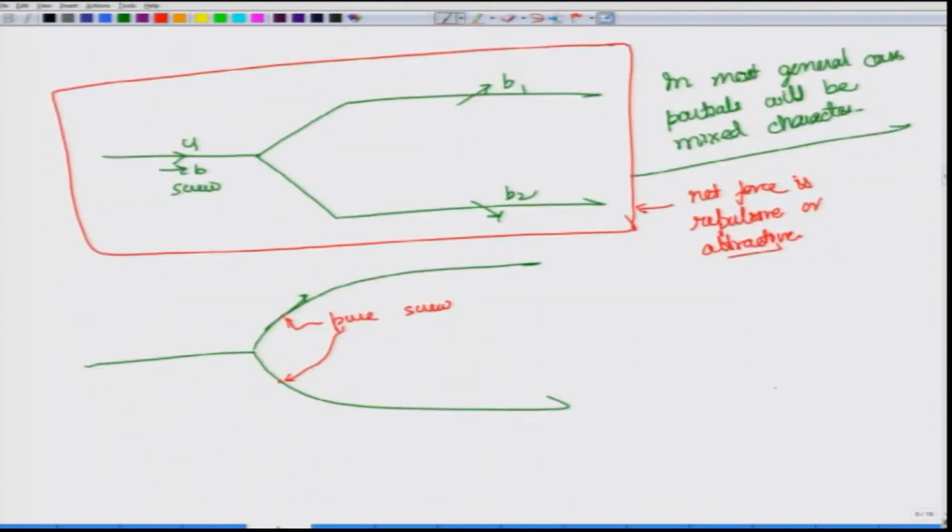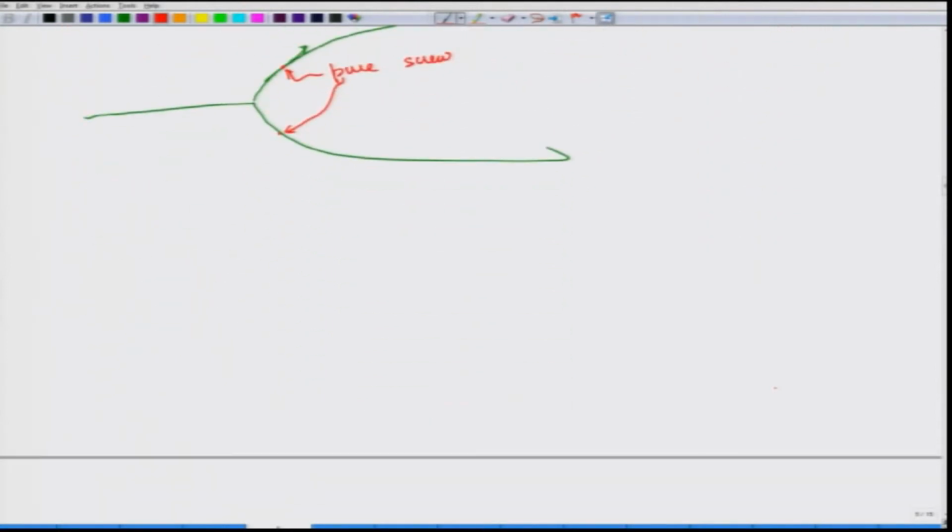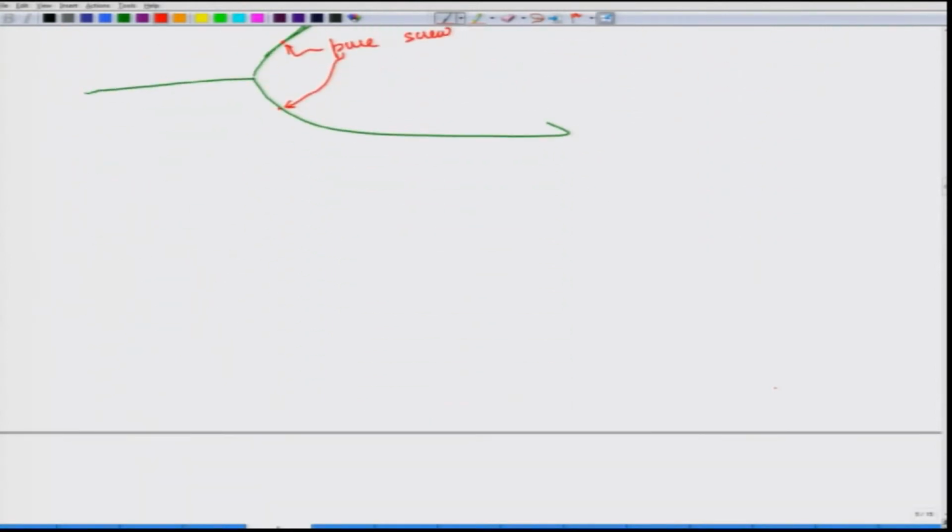Okay. So, a few things about this extended dislocation before we move on to finding out ways to describe dislocations in an FCC system. When a stress is applied, the extended dislocations move together.